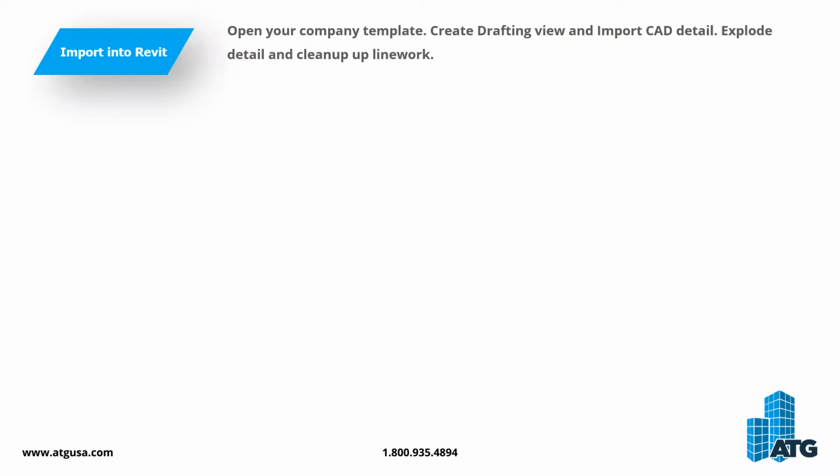So you can do multiple details in this one file, maybe have a base company template that you do this for, and import multiple CAD details, clean them up. And then when you get ready to insert it into your Revit model, you can insert it as a view. You can actually select the 2D views and basically batch insert or import multiple CAD details.